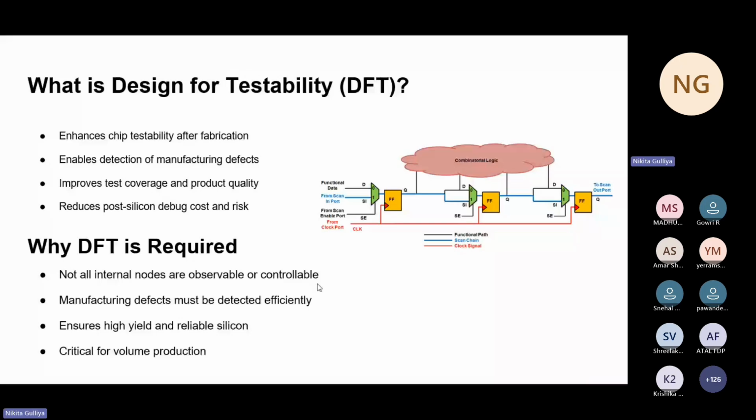And like I mentioned, scan insertion connects flip-flops into scan chains to improve controllability and observability. And LBIST tests logic blocks, while M stands for memory, so MBIST tests embedded memories.